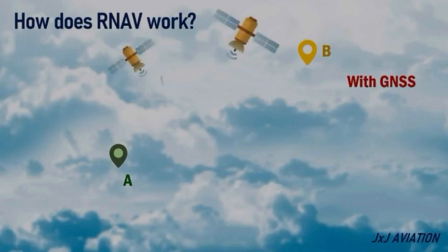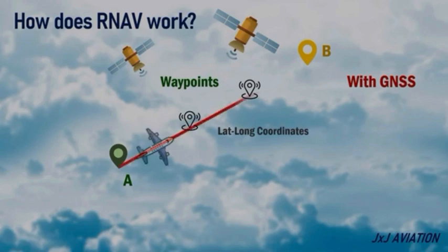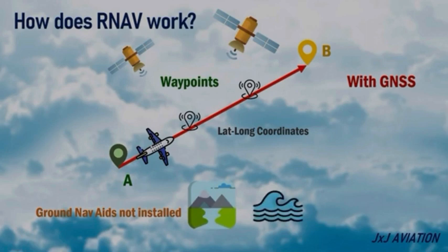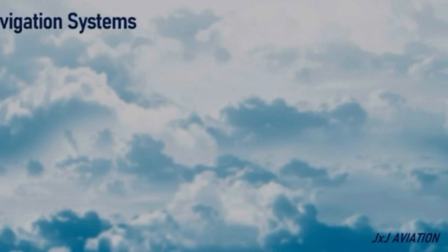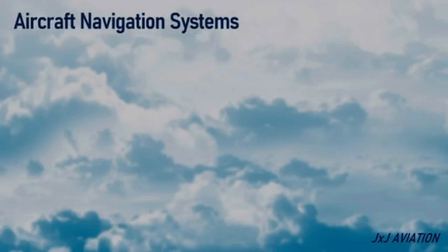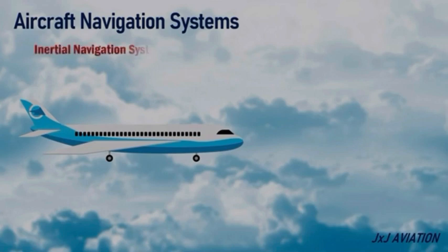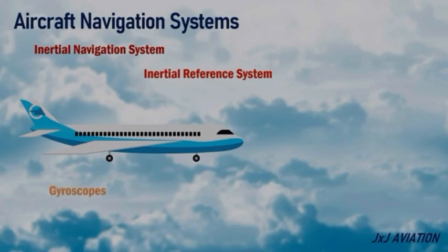The second good benefit that we can get from the PBN is that it avoids the need for developing sensor-specific operations with each new model of navigation system. So this means that if an aircraft is equipped with modern navigation equipment, we do not need to modify the ground-based sensors based on the navigation equipment that we have on board the aircraft. And the third good benefit that we can get from the PBN is that it allows for more efficient use of airspace and selection of more fuel-efficient routes.